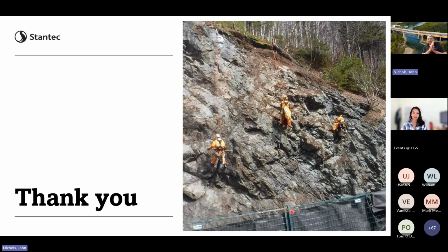Because when you pull that discontinuity together by tensioning the bolt and applying friction, you increase the strength of that rock mass much better than if you had a dowel. When you put tension on a rock bolt, you increase the friction and sort of the apparent cohesion of that surface. And you would do that if you had, say, a defined surface that you wanted to protect.